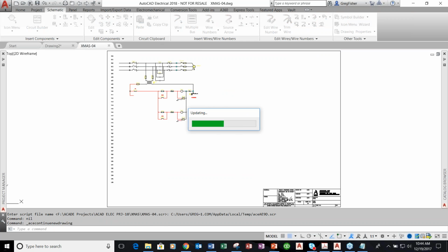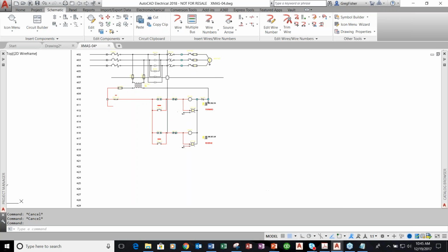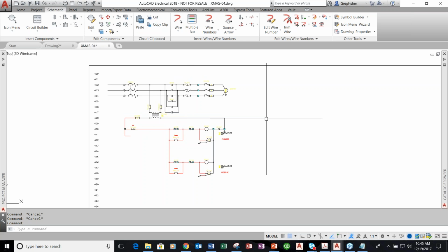And this is what I talk about. I constantly stress, build anything you want into a template. Here's a brand new drawing. I just started it. Half of it is done already. If you use some of the same stuff in drawings, in projects, create a template out of it. You can create a template out of anything that you want. If it's a panel, you use a popular size enclosure. Create a template where the enclosure is already part of it. You create a new drawing, it's already there.